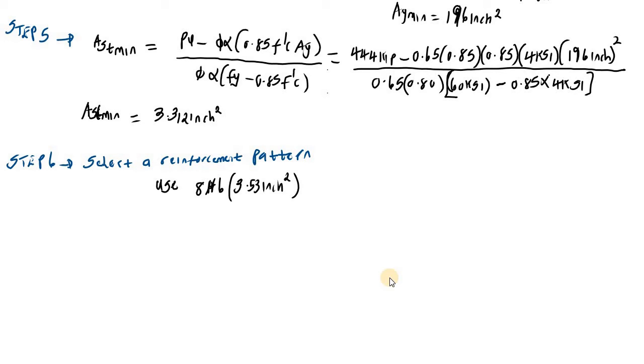So now this is step 6. Now for step 7, we need to select transverse reinforcements. We are now going to select the transverse reinforcement. Basically, transverse reinforcements are the stirrups. We are going to select this based on 2 parameters: the size of the ties, and the spacing from one tie to another. These are the 2 values we need to get.